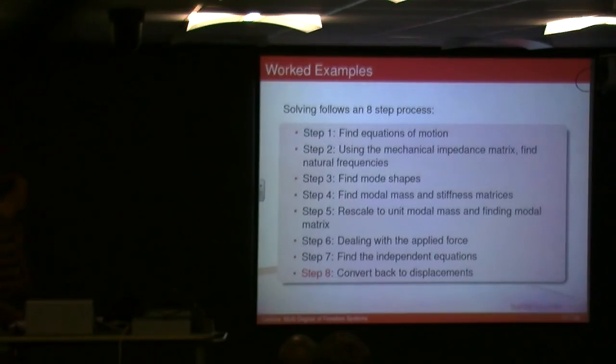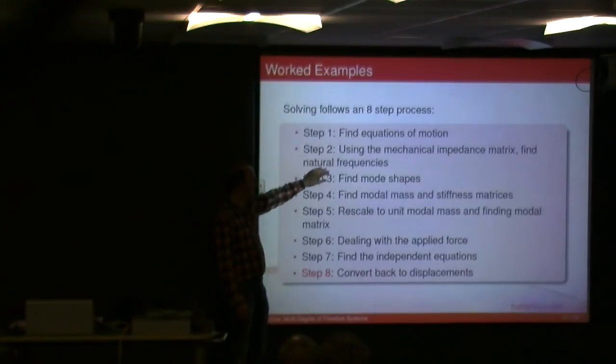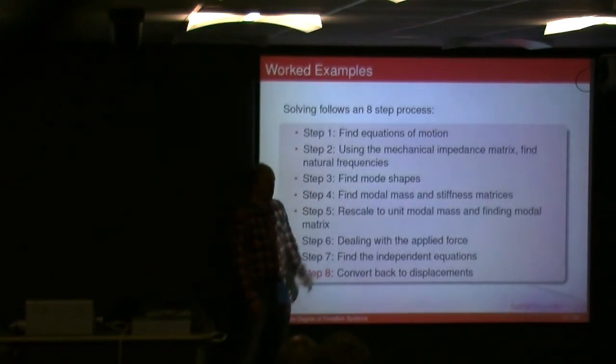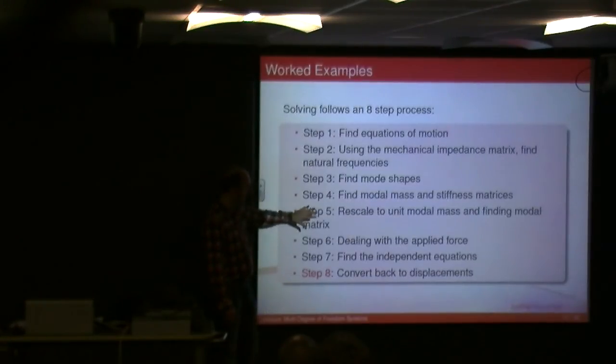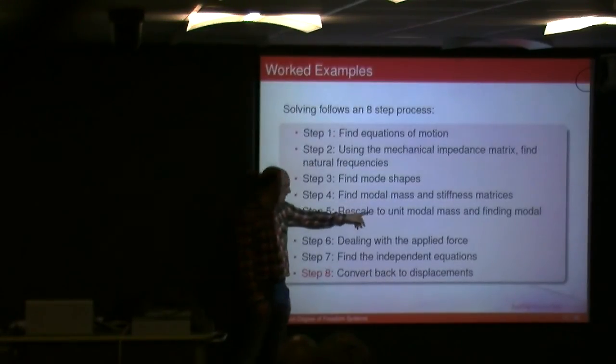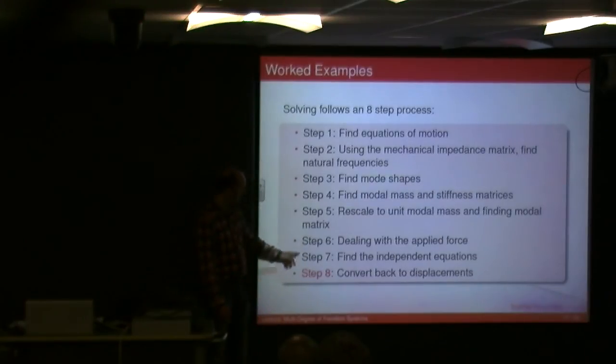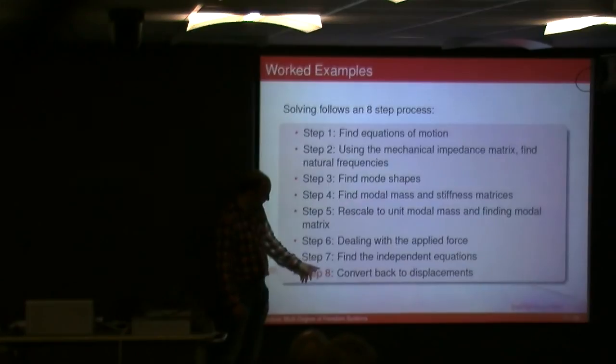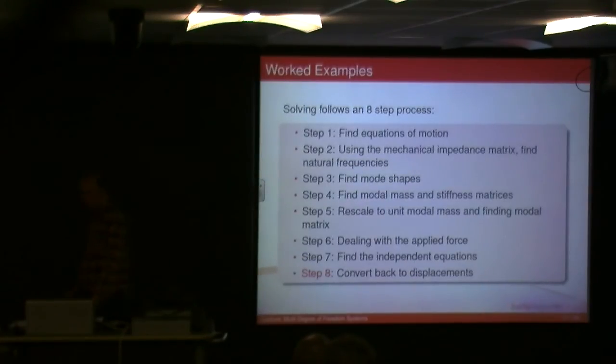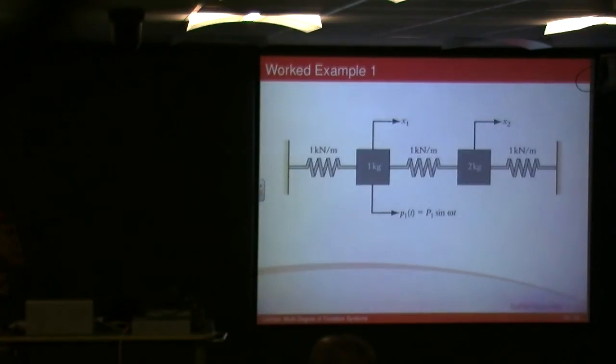So there's 8 steps. The first 3 steps are old stuff. Equation of motion, so using the correct method, natural frequencies, mode shapes. Step 4, find the modal mass and stiffness matrices. So we're going to deal with that. Step 5, you rescale the modal mass to unity, okay? And then you deal with the applied force. You find the independent equations, solve them, and then you convert back to your displacements. That's the process to go through. And each of the problems we're going to go through, we have that process.